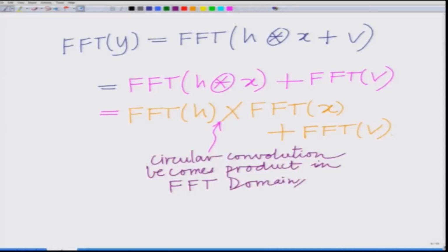Alright. That is the interesting aspect of OFDM, where we have taken a block of symbols, capital X0, capital X1, capital X2, capital X3, and performed the IFFT, or the IDFT, to generate the samples. To the samples we have added the cyclic prefix, and once you look at the output of the intersymbol interference channel, you see that what the channel is performing is equivalent to a circular convolution.